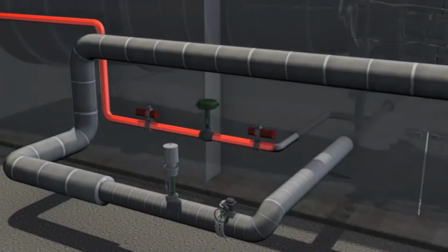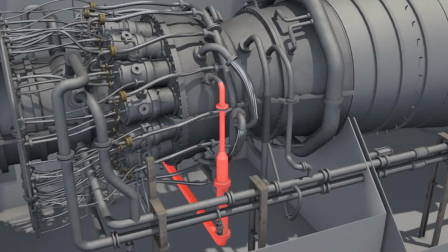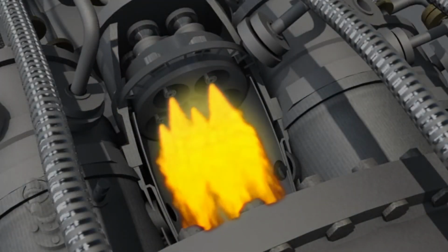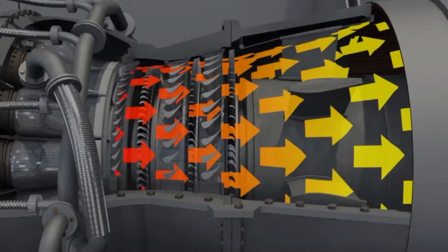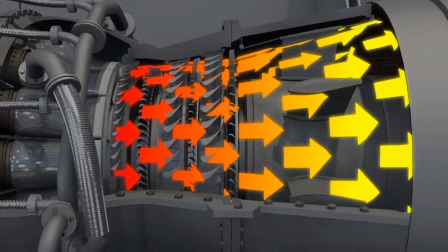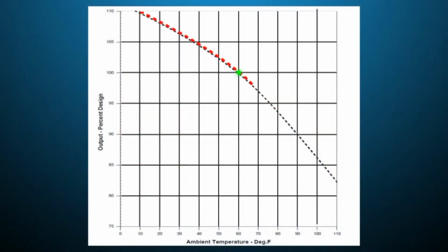Turbophase restores the mass flow that is naturally missing by injecting air into the compressor discharge. The gas turbine control system reacts naturally and adds a proportionate amount of fuel to account for the increased air mass flow, resulting in constant combustion and turbine inlet temperatures. The increased mass flow through the turbine section increases the mechanical torque to the compressor and generator.